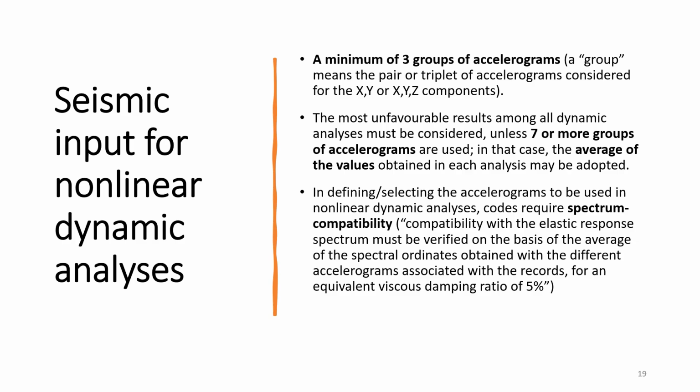The spectrum compatibility is a criterion that provides the selection of a number of records which are close enough to the target response spectrum we expect for the specific site of the buildings where we are going to use the analysis. And the types of accelerograms that are considered are also different depending on their origin.